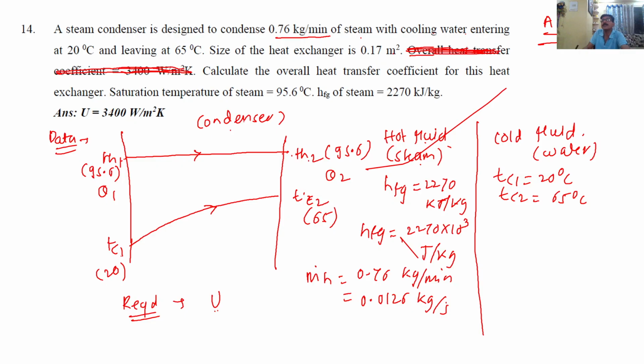Now I will make two columns, one for hot fluid and the other for cold fluid. A chemical specific heat 3.2. We don't know whether the chemical is hot fluid or cold fluid. Let's read the problem further. Enters a parallel flow heat exchanger at 150 at a flow rate of 30,000 kg per hour.